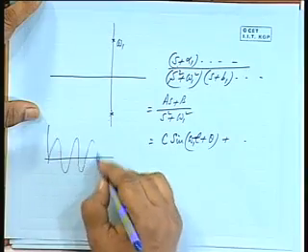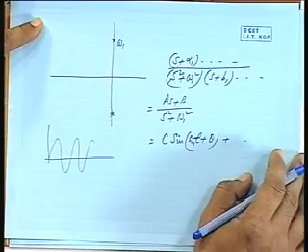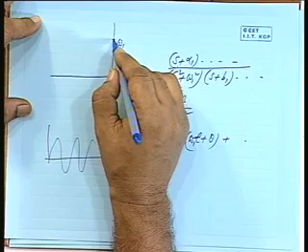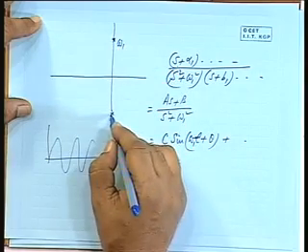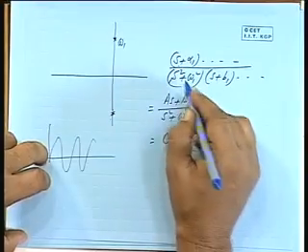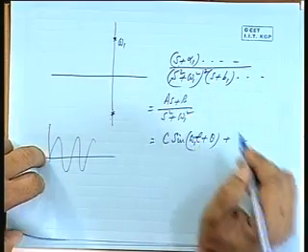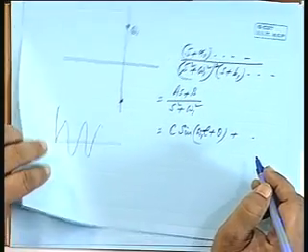Theoretically, if you have an LC network, you will have a sustained oscillation. So, it can have an oscillation like this, we call it a stable system still. Is it possible to have multiple roots on the imaginary axis? If you have, instead of S squared plus omega 1 squared, a squared term, then what happens?